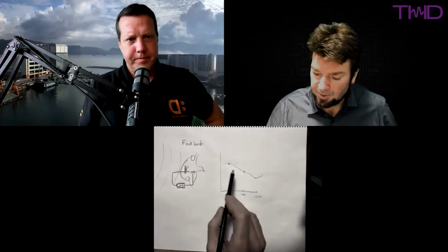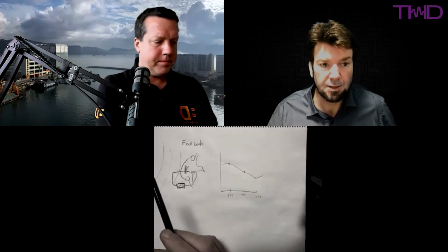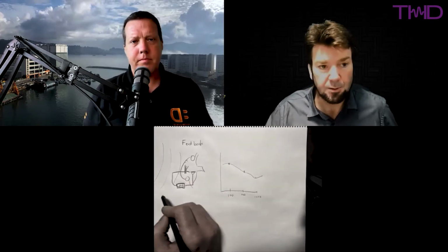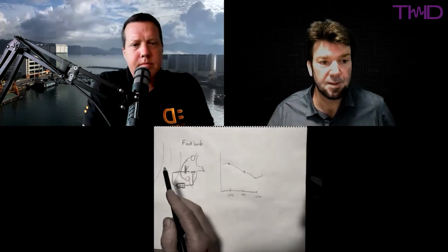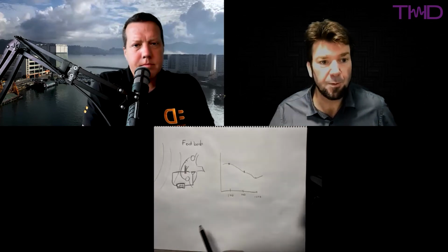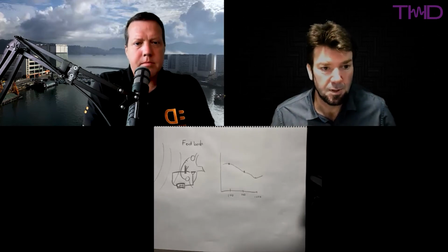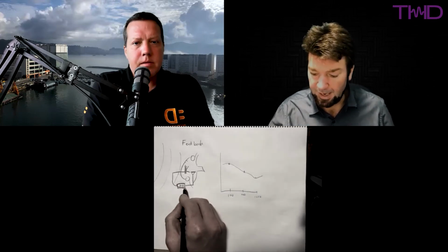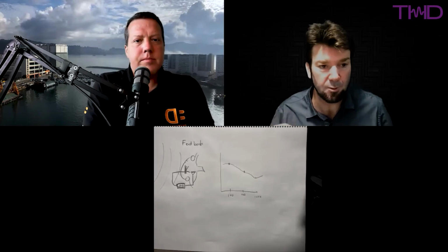So the concept with feedback is that you take a signal from the microphone and pass it through some filter to get an opposite phase signal out of the speaker. However, that signal out of the speaker at some point in the frequency range would reverse because of the acoustics of this system. Therefore, you have to diminish your gain through the filter at those frequencies so it doesn't become unstable or start squealing.